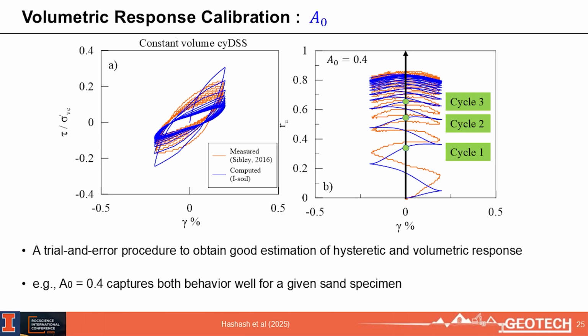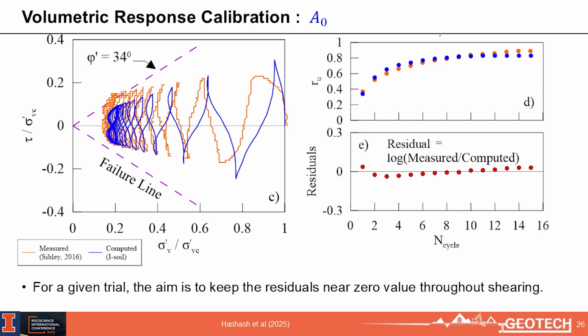We can do that. With this model, we did extensive testing. We can represent the cyclic behavior, cyclic degradation as a result, and also we can represent volumetric change, or in this case, pore water pressure generation. The vertical axis on the graph on the right is pore water pressure generation as a result of cyclic shear strain. And you see we're getting to an RU near 1. RU near 1 is a pore pressure ratio, meaning you have liquefaction, zero or near zero effective stresses, but you would start experiencing problems in your soil even when you're short of getting to 1. And it also causes huge numerical problems, so we don't want to have zero stresses running in our numerical simulations too much. So that cyclic behavior is very important.